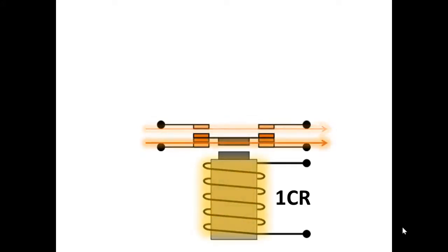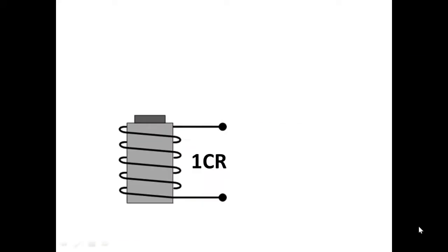If you energize the relay, that pulls the armature down, opens the normally closed, and closes the normally open. And now you have a set of contacts that have continuity when the coil is energized. Remember, the only real big difference here is that we eliminated the common, and now we have separate connections for both the normally open and the normally closed contacts.